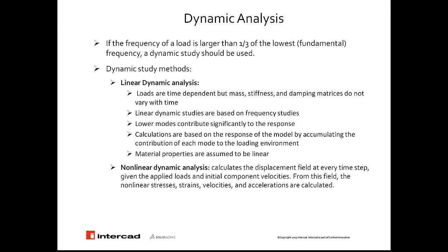In linear dynamic studies, loads are time dependent, but the mass, stiffness, and damping matrices do not vary with time. Therefore, these studies are based on frequency studies, and simply the first or lower modes of vibration contribute more significantly to the response of the structure. In such a study, calculations are based on the response of the model by accumulating the contribution of each mode to the loading environment.